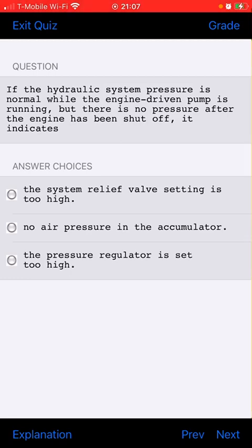The component that determines the pressure level in the cabin is the cabin pressure outflow valve, definitely the outflow valve. Placing a piece of cloth around the stainless steel control cable and running it back and forth over the length of the cable, oh my God, this is very dangerous. But we check for some broken strands when we're doing that. So running it back and forth along the length of the cable is generally a satisfactory method of inspecting for broken strands.